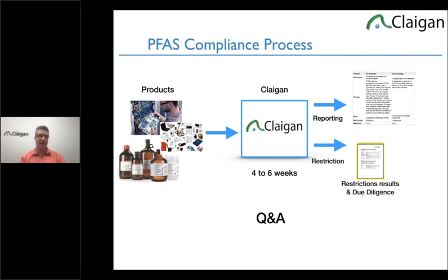It's a manufacturing aid to create the powder originally in the PTFE part. So PTFE is a PFAS. It's a polymer. It's reportable, but it's not restricted outside some pretty specific applications around food contact and fabric. It may contain PFOA, and it's a risk of containing PFOA, but it doesn't have to. It's not necessary. It's just a material that can be used as surfactant to control the powder size of the PTFE, which is important for processing before it's cured into the physical material.